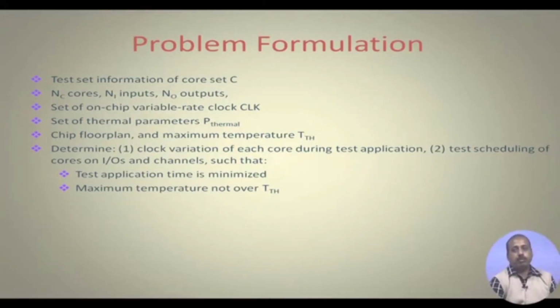Maybe if that maximum threshold is say 85 degree centigrade, we will try to operate within say 75 degree centigrade, being pessimistic, because in actual testing session it may become about 80 or so, but still we have got a guard of 10 degrees, so that this DTM is not invoked and the test session is not stopped in between.